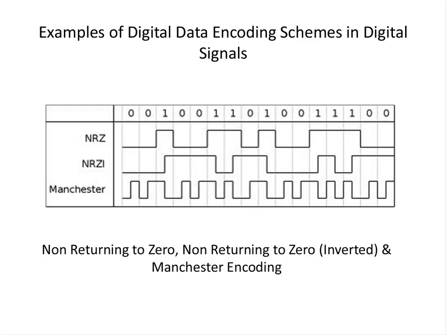What is the logic? Mostly about not putting charge on the wire. If you send a whole stream of 1s and keep saying 5 volts, 5 volts, after a while the wire will get charged. So it won't be as receptive to your signal anymore. There'll be a quote-unquote noise on the wire. So if you have 2 consecutive 1s, bring it down so that it keeps neutralizing. Those are types of logic people have used to come up with more and more complex schemes.